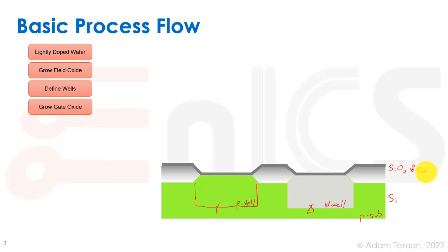And even in the past, when we had very old processes and it was much thicker, we were still able to make this really nicely with very few impurities, because any impurity inside there is going to affect our VT and ruin our transistors. So one of the reasons silicon really was dominant was because we were able to grow such a nice gate oxide. And we grow it on this whole entire huge wafer in a very, very uniform fashion. So we did that without any photo mask.